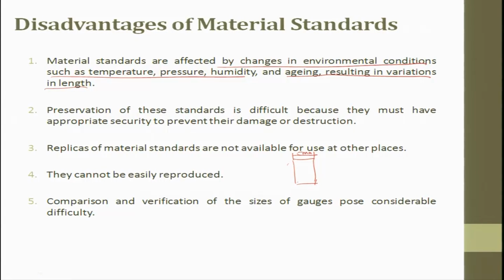Disc of 5 millimeter length, and the diameter is around 20 millimeter. You want to maintain the flatness between these two. These two surfaces should be parallel to the highest accuracy of 1 micron. We cannot generate this surface so easily.